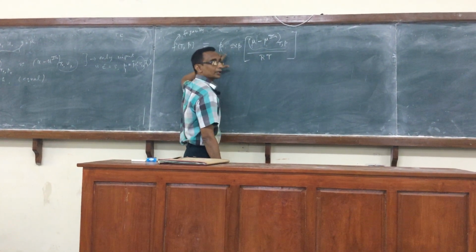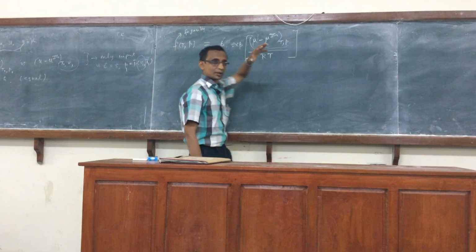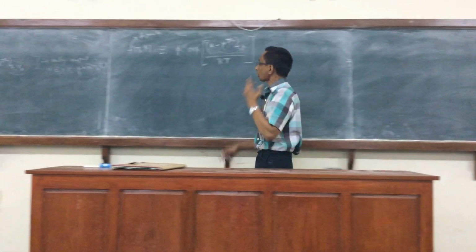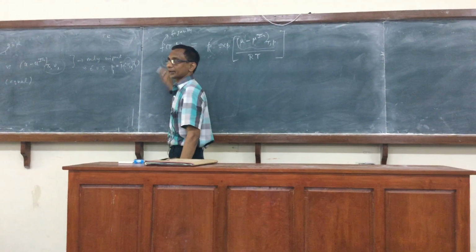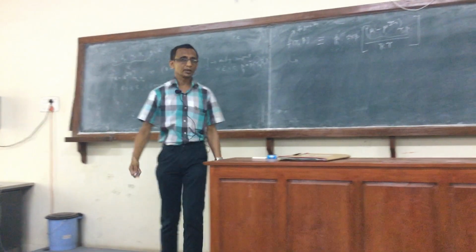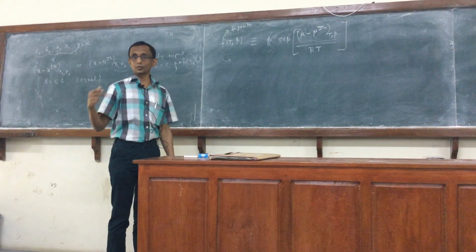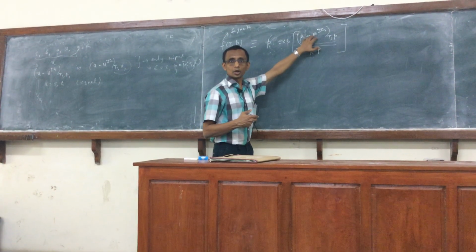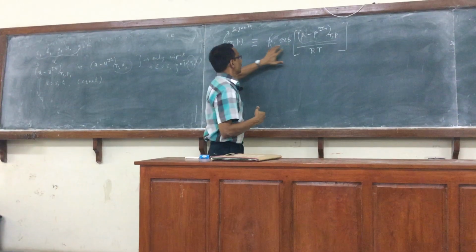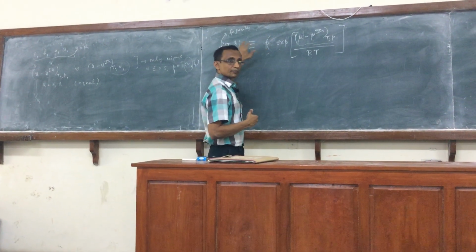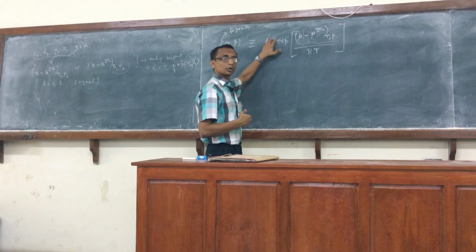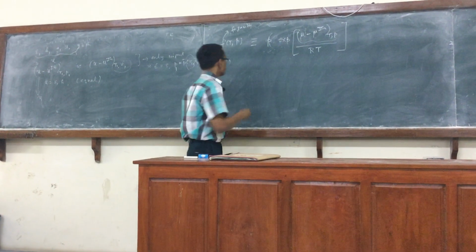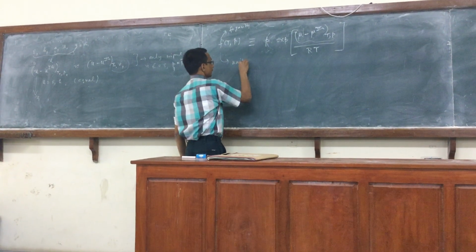However, pre-multiplying that exponential is the pressure of the actual state of the substance. So clearly, what are the units of the fugacity? The pressure. So it's very important. Whatever units you use, this of course has to be consistent, joule or kilojoule or whatever. The units of the fugacity will be determined by what units you choose to express the pressure in. So it has the same units as the pressure.